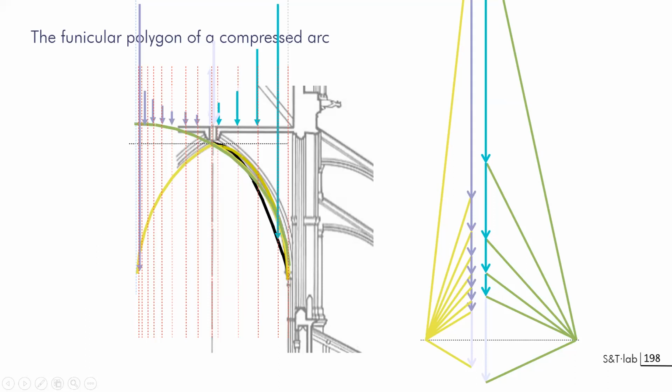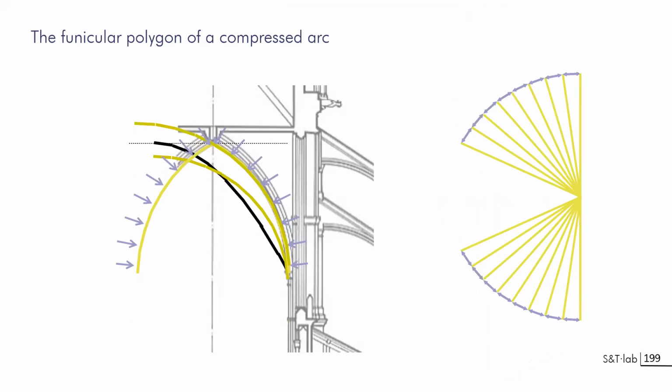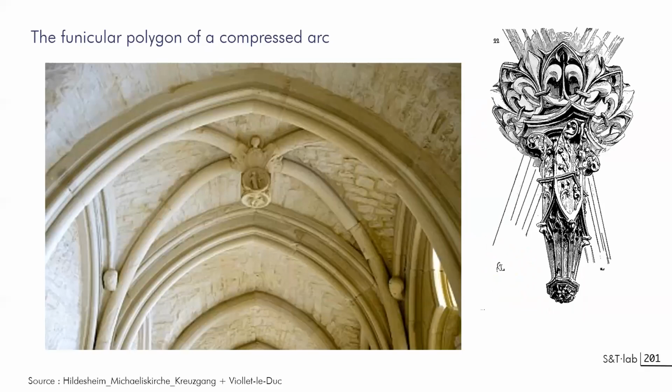You can use also this kind of system, and if I'm drawing a kind of pressure, it doesn't make sense. It's just for the exercise, you see that it's not closed, but this will reveal that you will need other forces in the middle. And that's the case also with the pointed arch we have seen before. And one of these applications could be what is called the hanging keystone, that is an additional loading at the very middle of the arches. You have examples of several approaches. This will be in Paris also, in Saint-Laurent and Saint-Eustache on the right, that will give you elements of equilibrium.